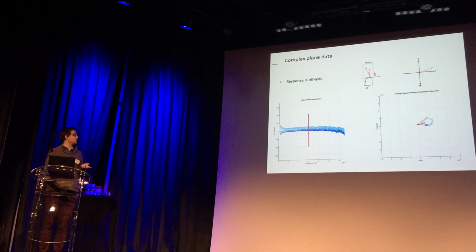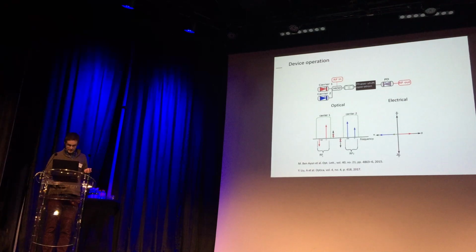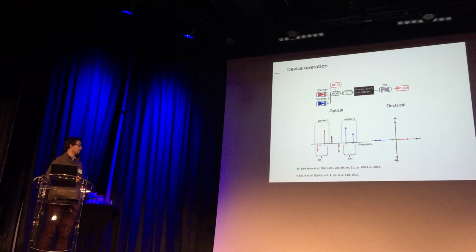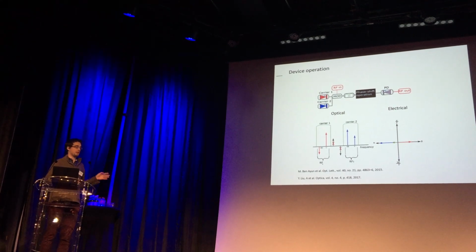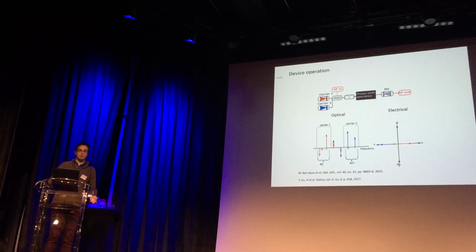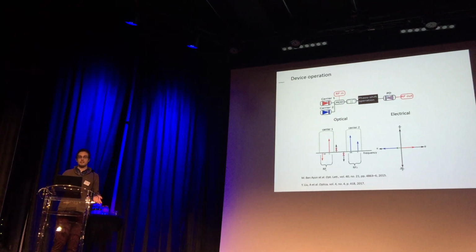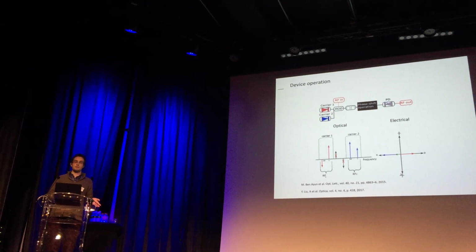But the other issue is, if you go back to this diagram here, you can see that there's an inherent trade-off between link gain and phase enhancement. So this net resultant vector here, I mean, this is only a graphic to demonstrate the idea, but even still, it's much smaller than these other vectors. So the trade-off is link gain for phase enhancement. So that's another potential source, because when you're dealing with only one laser, there is no such destructive interference.